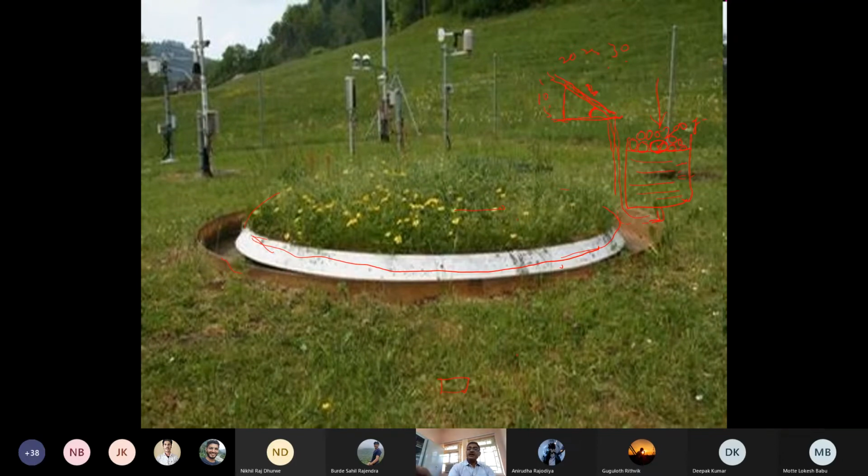We make a relationship between this inclined angle manometer tube length, which shows the head of water at different additions of weight, and the same for removal of weights, that is basically showing the ET. So addition of the weight is irrigation water added to the lysimeter, and removal of weight is simply evapotranspiration. That is what we resemble with this arrangement in the lab experiment.